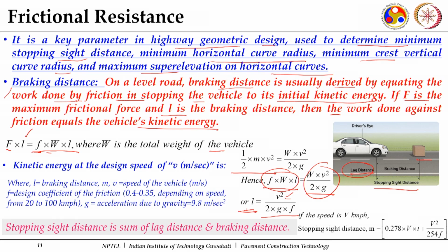So, after applying the brake, which is known as my braking distance, I need this much length to safely stop my vehicle before encountering any damage with any obstacle on the road surface. So, this is what is given here. Stopping sight distance, usually when v is in kilometer per hour, is the distance travelled at the standard speed for the initial time, and this is the distance travelled during the braking action. On the basis of it, I can work out this particular braking distance.